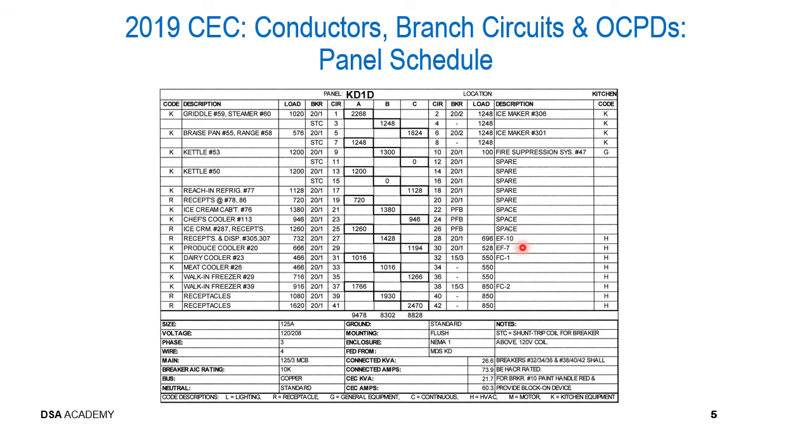And it's not uncommon to see exhaust fans and fan controls. This particular breaker here is a 15 amp 3-pole breaker, and you can see it's fed from circuits 32, 34, and 36. So you've got a 3-pole breaker, 15 amp, so you would expect to see 3 breakers with tie bars across them.